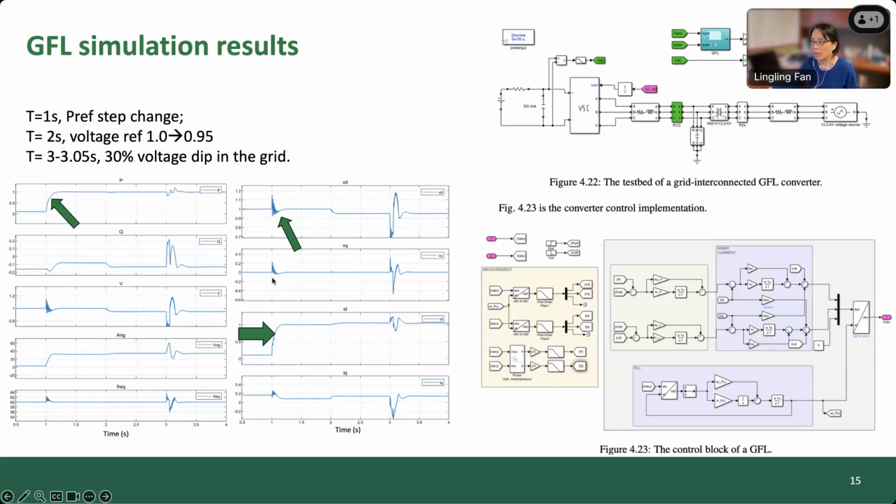because you will see the Vd voltage starting to decrease. On the other hand, Iq is trying to stay at zero. You have the PLL make this zero. But the voltage starts to decrease, and because we are using a PV controller, a voltage controller, the Q-axis current will also change, trying to decrease. So you inject more reactive power into the grid, and the purpose is just trying to make the voltage go back to 1 per unit, the original value. So this is what happens when you design the control and some references change.